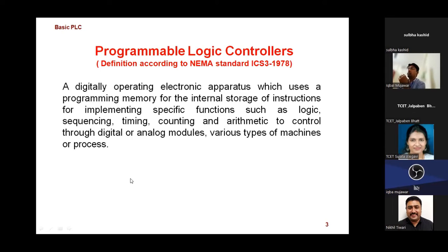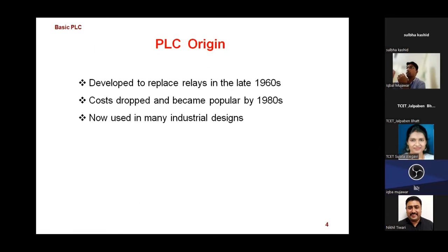Similar kinds of things we can do with a regular controller also, like an 8051 or any other controller, which electronics people know better than me. But what will happen to withstand that mechanical environment, the high temperature, the vibration, all those things? Because of that, a special kind of controller is designed for industry, that is a PLC. Ultimately, this is also a controller, and other controllers are also there in the market. They can do similar kinds of tasks, whatever I explained right now in that definition. But to stand that environment, here we need to use the PLC, programmable logic controller.